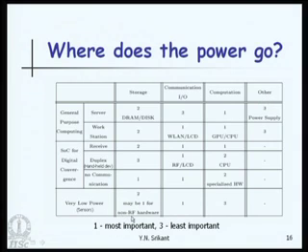So, a sensor network system will have very little storage. So, it is not very important to have more storage, so this could be 2. For example, there is not too much storage on a low power sensor system. But if it is a non RF device, there could be a lot of storage. So, that is why it is 2 for sensor devices, and for non RF hardware it is 1, that is most important to consume power. Communication is the highest power consumption apparatus on the sensor, the transmitter and receiver, whereas computation is least important. So, it does not take too much power to compute whatever it has read.